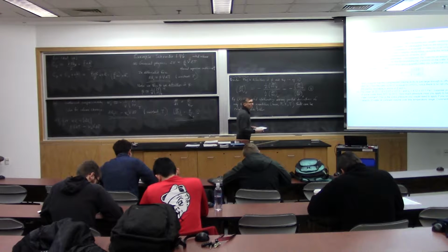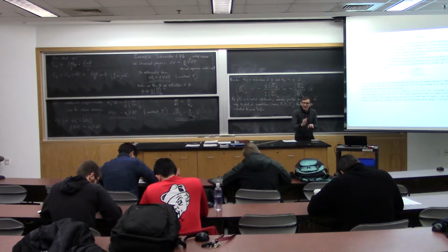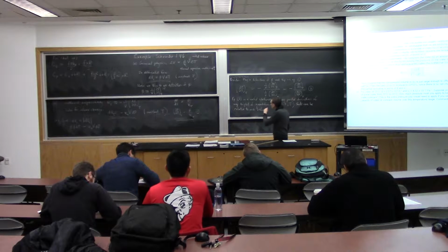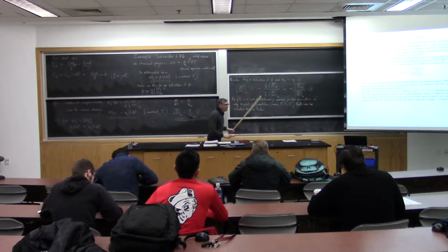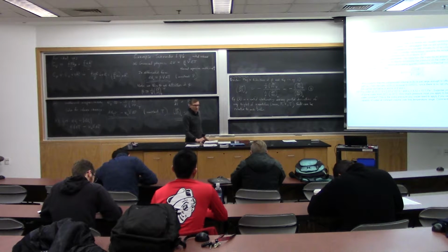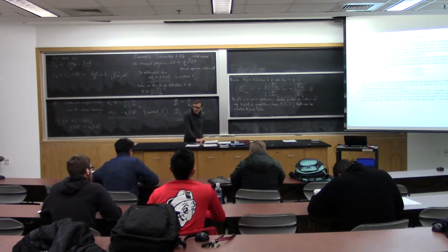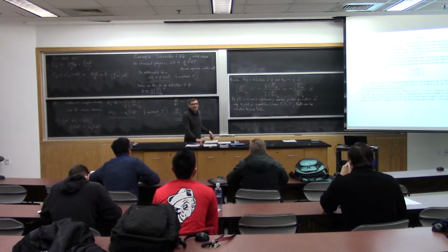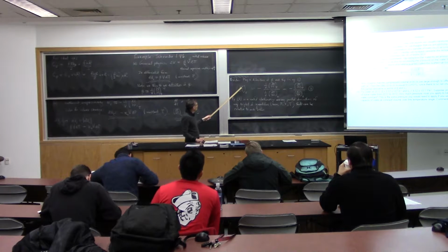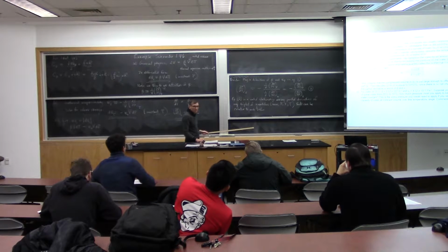You need something called an equation of state that relates P, V, and T in this case. Okay? Now notice what it says. If you look at it a little bit, you see a pattern in this relationship amongst the partial derivatives. And if you look at that pattern a little bit, you say, oh, I can kind of see why that pattern is correct. What I have on the left is the partial of P with respect to T, holding V constant.